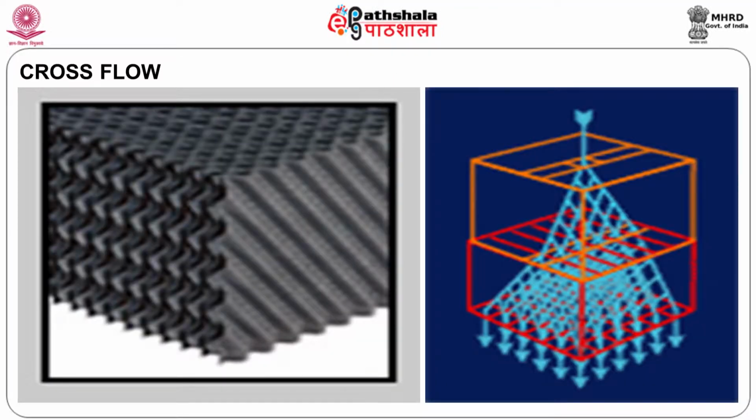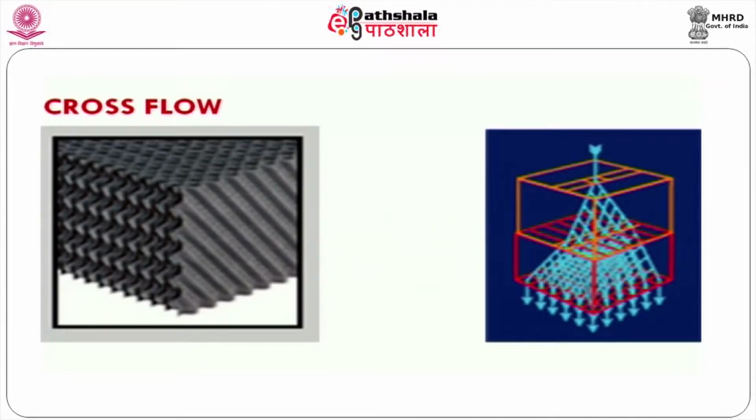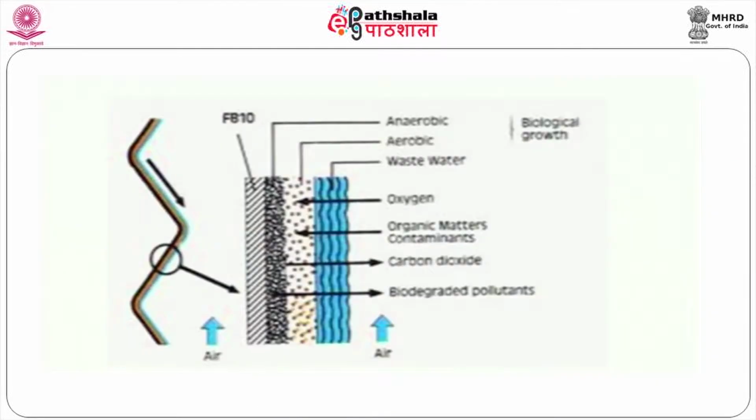Here, by spreading water into a larger area, into the packing media, we are splitting as well as joining flow at each nodal point. So, this will definitely create some sort of mixing while allowing water to pass through the packing media. So, this is a peculiar advantage of cross flow media when compared to other flow patterns like vertical flow, wavy flow, as well as spiral flow. So, with the help of this definition sketch, we can understand the working principle of the trickling filter.